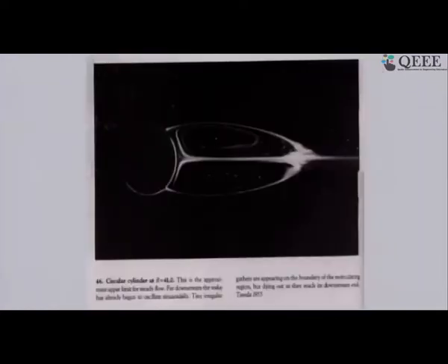This is at Reynolds number 41, and this is another trick that some engineers have used to do this research. What they have done in this case is they have put a dye in the water flow and then seen how the dye gets off from the surface. Here they have coated the cylinder with some material, and then that comes off, and you can see that this is going off like this. Some of it comes back and goes like this here, and this one is going around like this. So the attached wake is still there at Reynolds number 41, but what we don't see here is that slight oscillations have started to come in. This picture doesn't show that, and the separation point is at about this point, slightly behind the top of the cylinder.